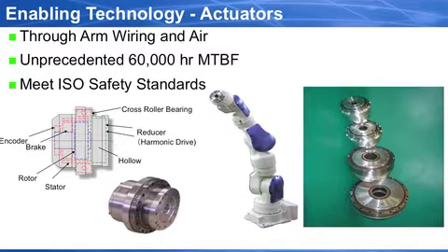You see, as you add that 7th axis, you now have to deal with cable management much more so than you did in 6 degree of freedom machines. Because they're so redundant, you could tie cables in a knot with a 7 degree of freedom machine.